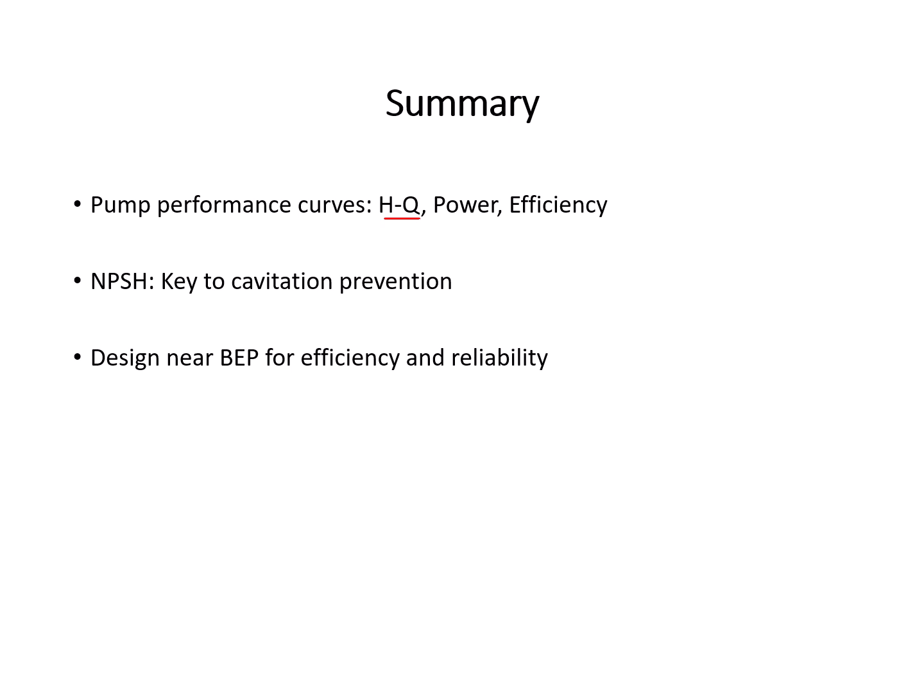And we saw how the head and Q vary in centrifugal compared with positive displacement pumps. We also showed how the power and the efficiency are calculated, and you have to select your pump so that the maximum efficiency of the pump matches your design flow rate.